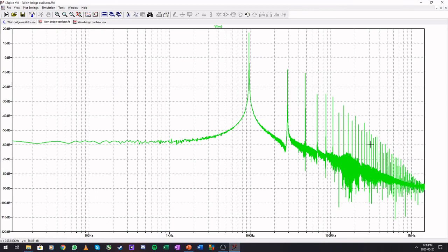Some of this is noise, especially here at the bottom, so you can ignore it. Stuff that is smaller than minus 40 dB is typically in the second decimal for this problem and does not have such a large influence. There are quite a lot of them, so it can amount to a lot. Remember that this is expressed in dB, but if you convert it back to volts, these are the RMS voltages of our signal.